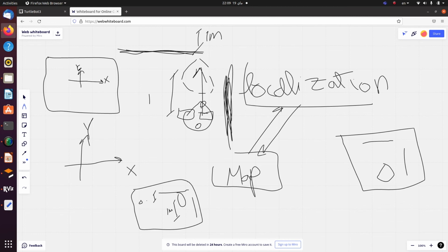So the origin of the map itself, when you're using the map server, has a picture format. So in picture formats, the origin of the picture is somewhere here, right? At the beginning or at the end, at one of the edges, at one of these vertices. That's usually the case for PNG, JPG, and PGM and such extensions. Usually the origin frame of that image is located at one of these vertices.